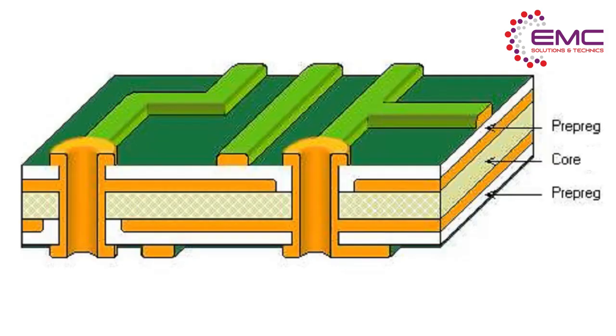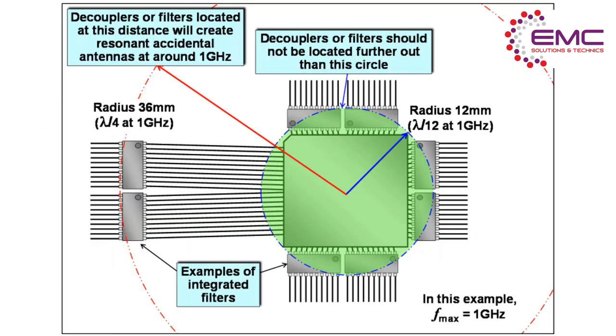If a 2-layer board is used and a complete layer of ground is not possible, then ground grids should be used. If a separate power plane is not used, then ground traces should run in parallel with power traces to keep the supply clean.